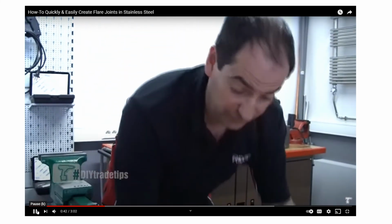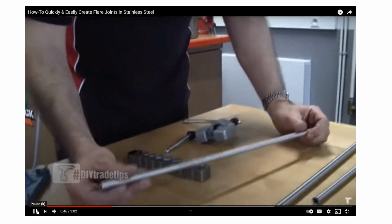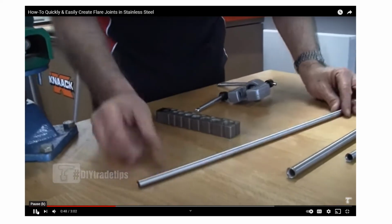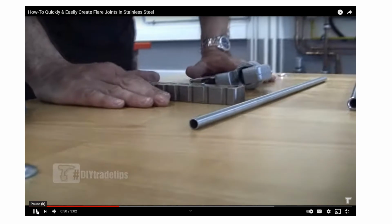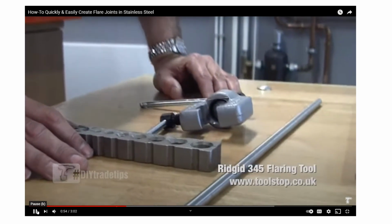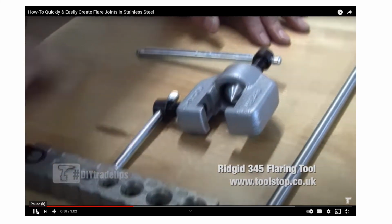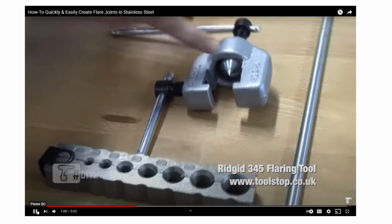So we're going to form a flare. So a piece of stainless steel tube we've got here. This is 3/8 tubing. And to do it, we need a flaring tool. Come in two halves, two bits to a flaring tool. This is the Ridgid model 345, and it has the flaring bar and the actual flaring tool itself with the cone.